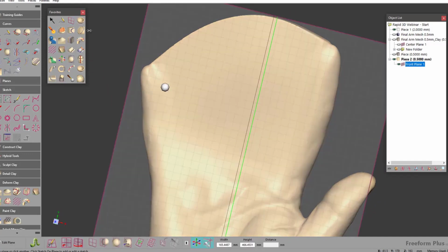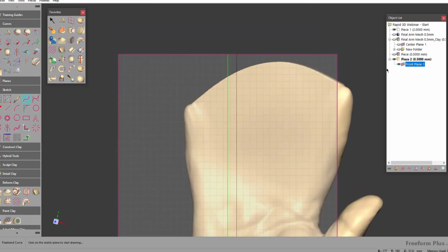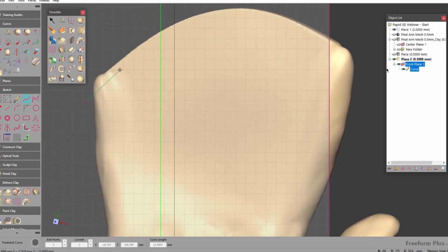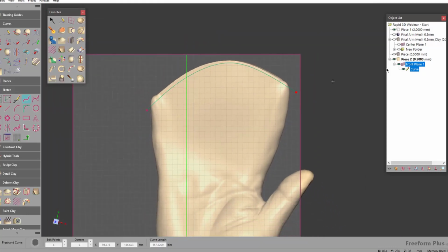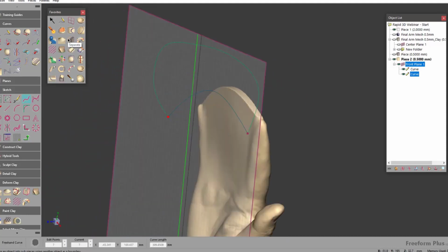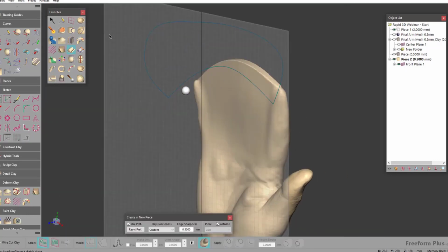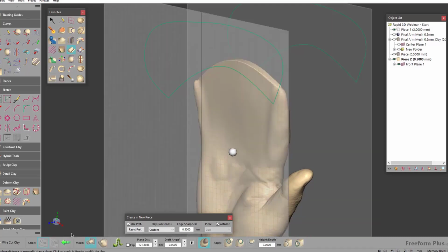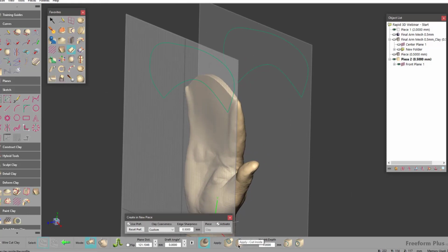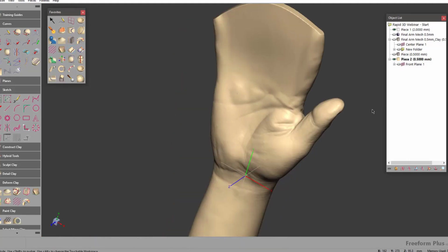And this is where the software utilizes, again, more CAD tools. I can go ahead and throw a plane normal to my view, and then I can come in and sketch directly on that plane. And I'm just going to trim off that top area all as one. So you see I'm going to go ahead and hit N there and then draw another curve around that way. And then I'm going to use what we call wire cut clay, which wire cut is basically just an extrude. If you've used a CAD package before, I can select my sketch and then I can extrude a shape. And in this instance, I'm going to say I want to extrude cut. And then it will cut that top area off and just cut a nice clean shape.